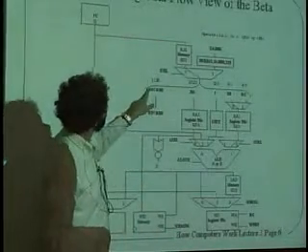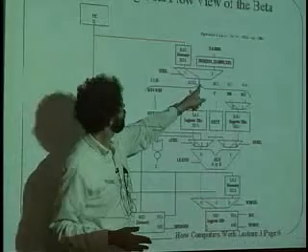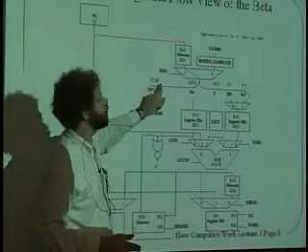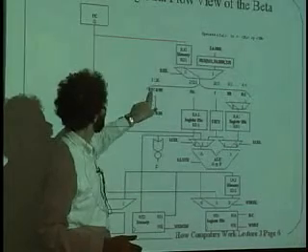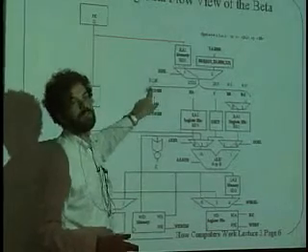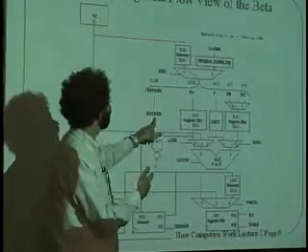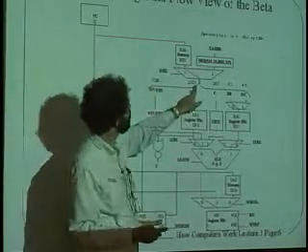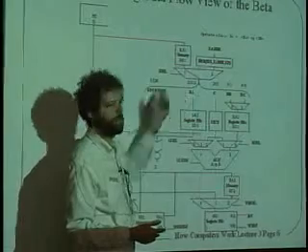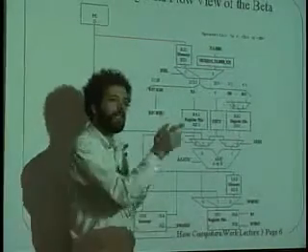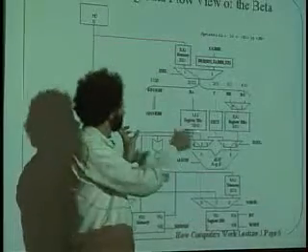Well, it takes those 32 bits that come out of this particular selector, and it takes the high order 6 bits, bits 26 through 31, and it calls those the opcode. Because if you remember, the left-hand 6 bits of this thing were the opcode. It takes bits 21 through 25, which are the next 5 bits, and says those are register A. So it's just breaking apart this 32-bit word into several fields.